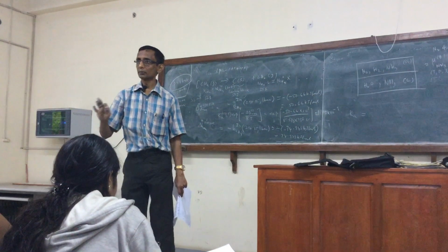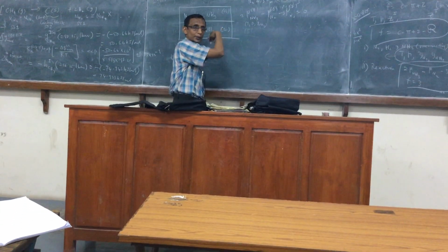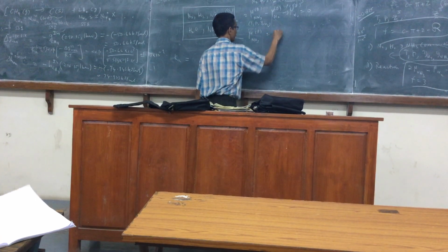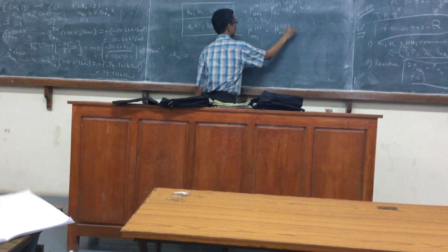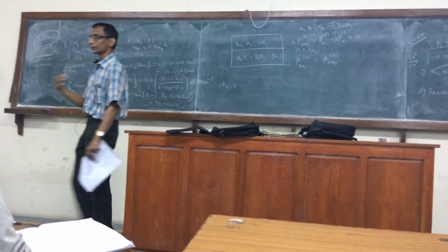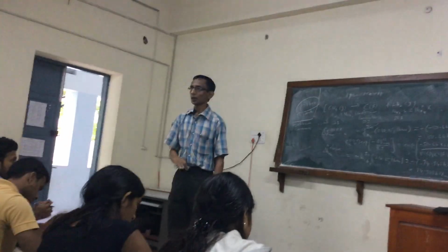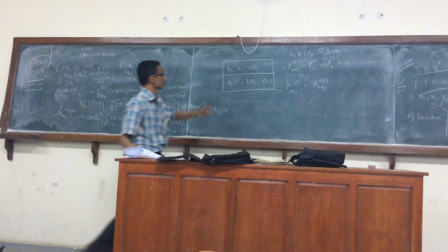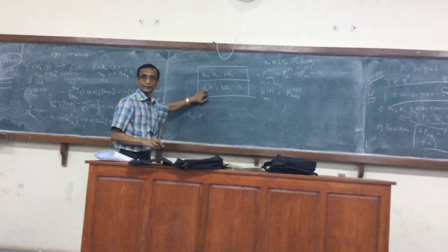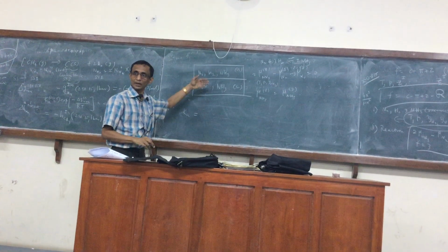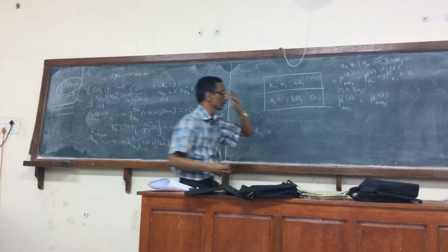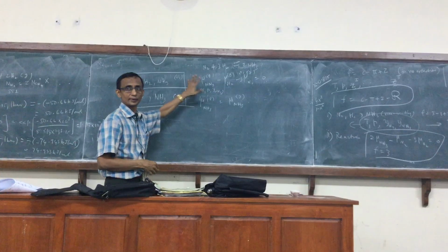So that is one equation, and another equation is for ammonia, the only component that I am assuming is present in both the phases, so I have equality of chemical potential between the liquid and the gas. We have now two equations. This is how the combined effect of chemical reaction and phase equilibrium would have to be taken into account. Of course, if, as he assumes, nitrogen and hydrogen are also present in both the phases, then we have to have the equality of those chemical potentials also. That will be even more complicated. So I have simplified it so that we just consider the effect of both.